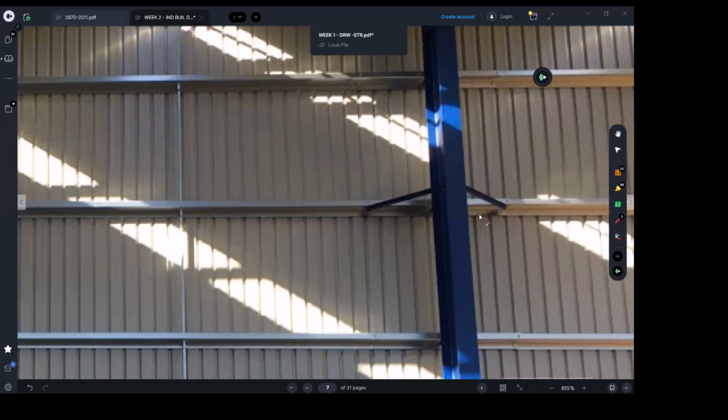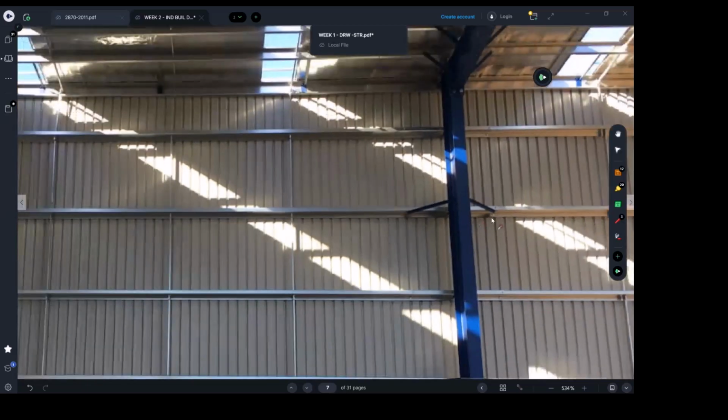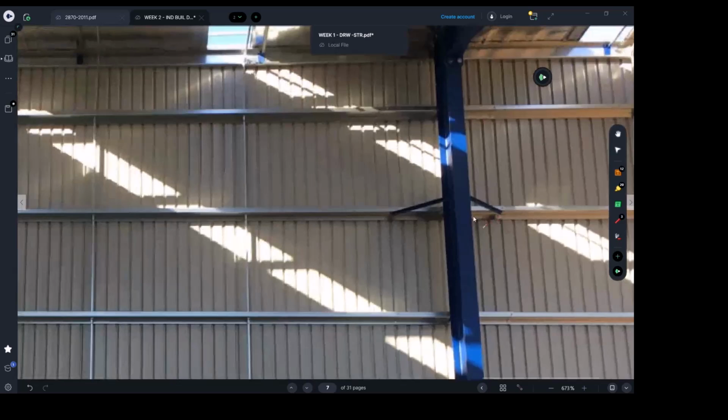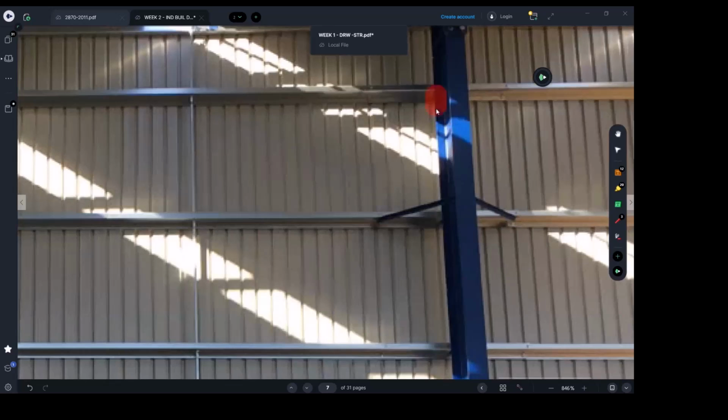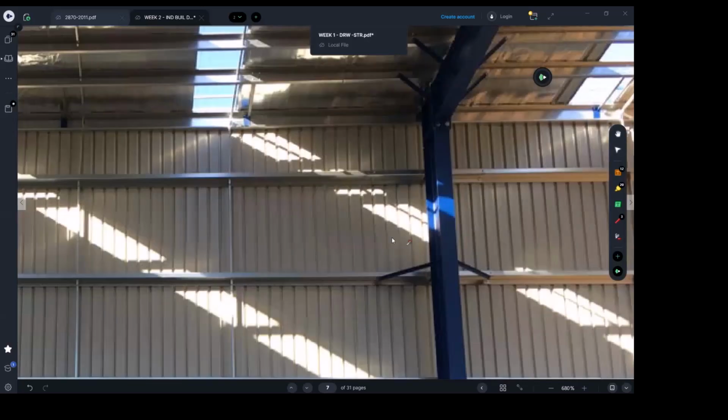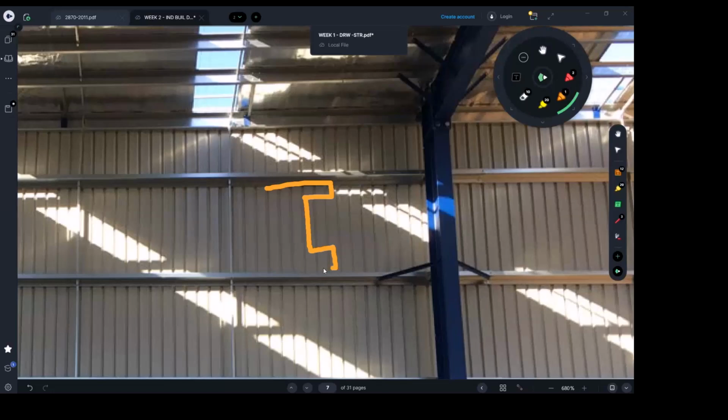Now, this is a bit critical, and we're going to talk more and more about it maybe during the workshop. What I want you to understand here is we are actually laterally bracing the columns from both sides, the far end and the close end. The far end is that flange in the back. The flange, you know what flange means, guys? The flange, if I quickly drew a section, this is a section of a column. Yeah, that's the cross section for a column when I cut it here.